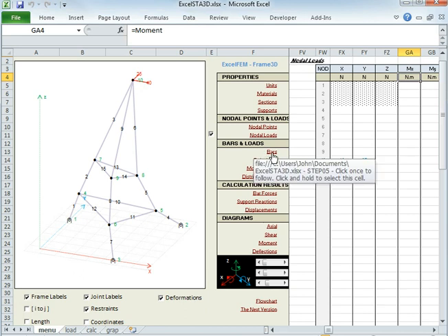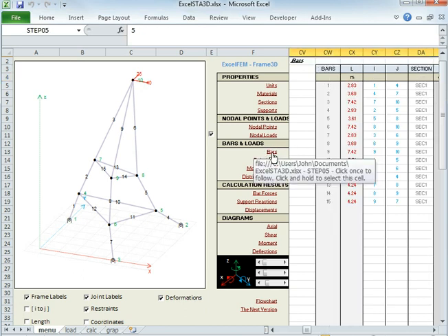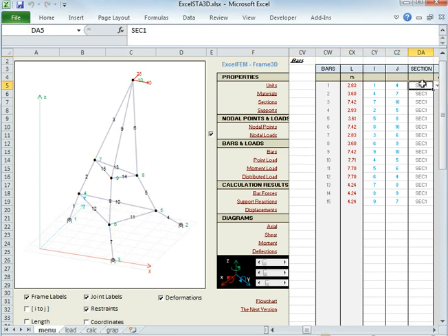And now let's go define some bars or elements, but there's a bar number here, or element number if you like. It tells you what the distance is. It tells you that it's running between two nodes, 1 and 4. So let's take this example here. Bar number 1, or element number 1, runs between node 1 and node 4. There you go. And the section that is being used is section 1, so it's reading from that previously defined